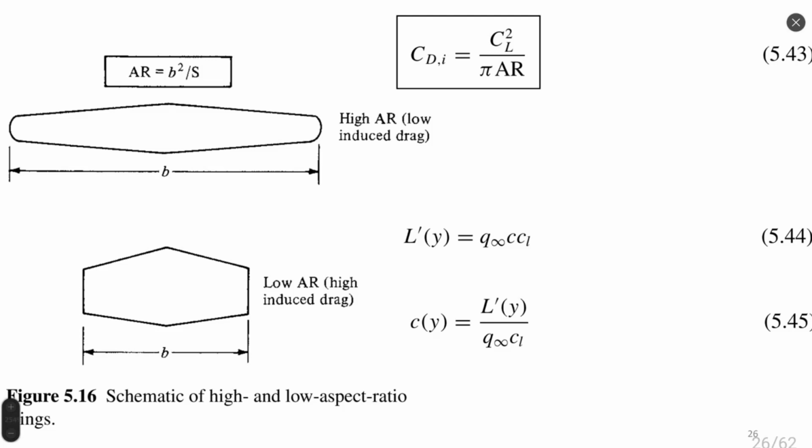I think equation 43 is a culmination of aerodynamics, at least aerodynamics for the wings, saying to us that losses on the wing will always exist. No matter how you improve your aerodynamic structure, you will need to fight at least this induced drag existing just because of the wing geometry.